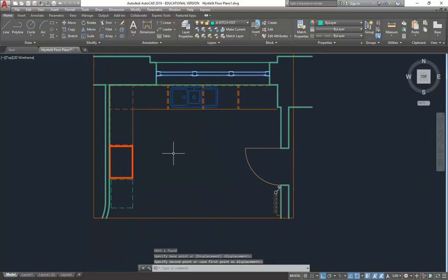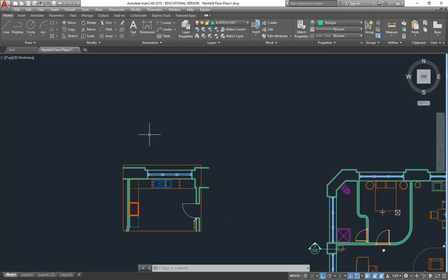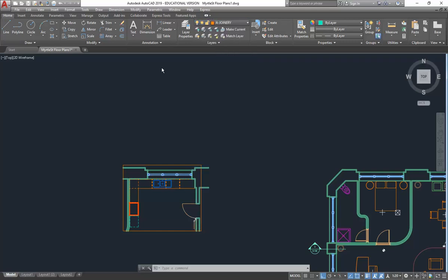Okay, but that might do for now. Okay, so I've got a basic set out, and then we'd start projecting the elevations off. I'm not going to show you all of that, but start to think about how you could draw the things that you've hopefully sketched from what's on the board. So there, I'll just do a very basic set out back on my maybe joinery layer for the line of the floor, and then offset 900 for the height of the bench.